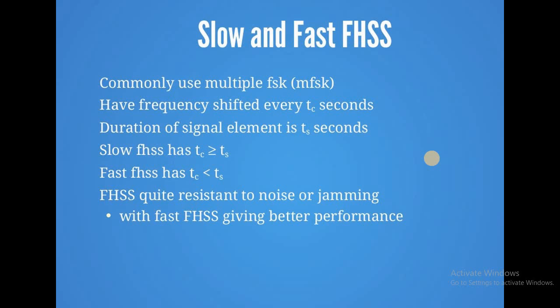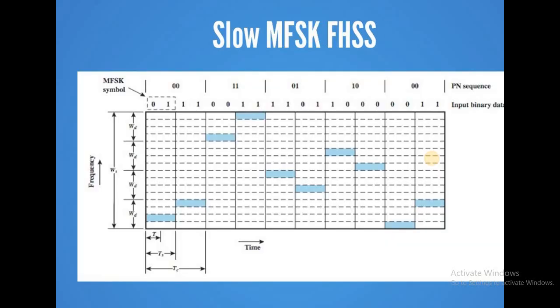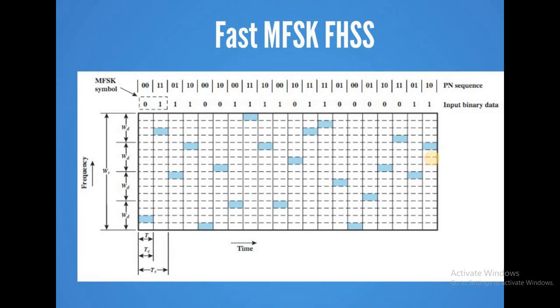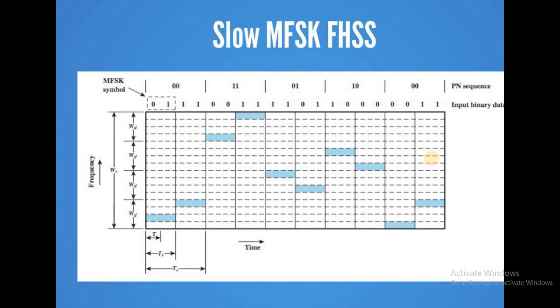This is the hopping time and the dwell time. The slow time is referred to as the hopping time. In slow hopping, multiple bits are transmitted on the same frequency. In fast hopping, individual bits are split and transmitted on different frequencies. This is the slow frequency method, and this is the fast frequency method. Bluetooth technology is an example, and GSM is a slow frequency hopping method.